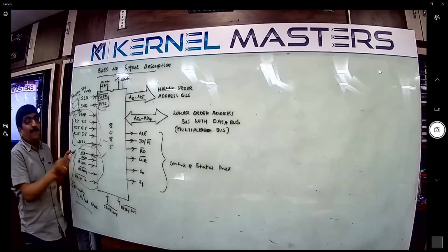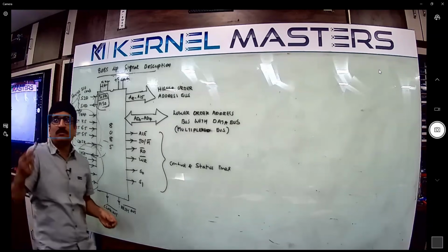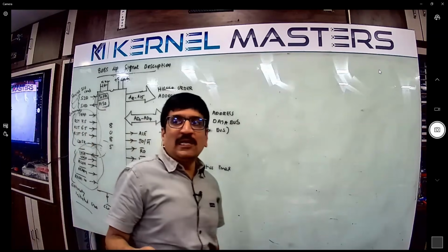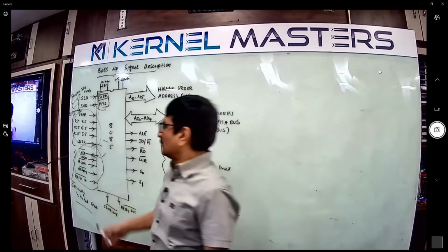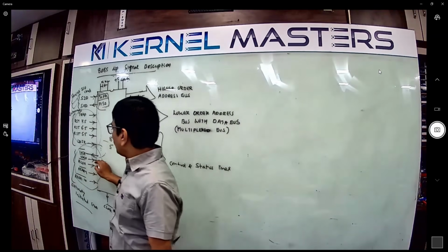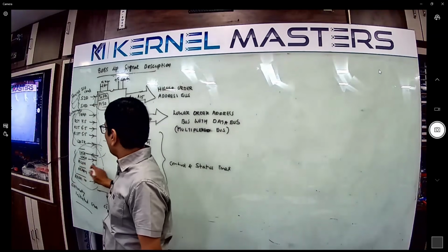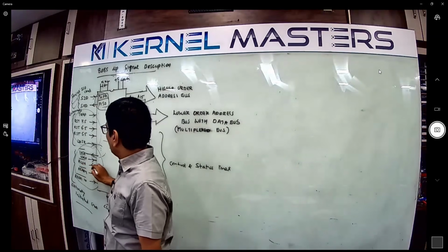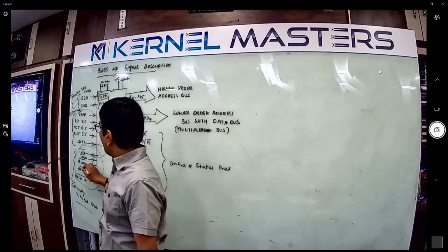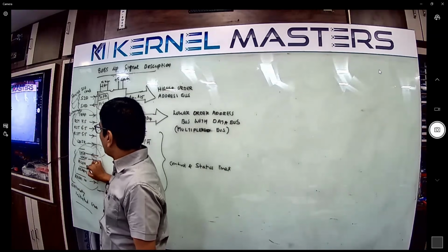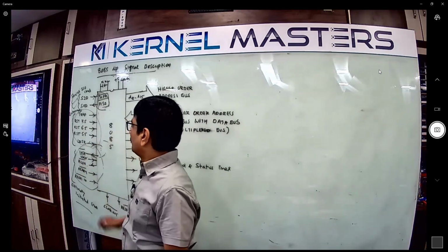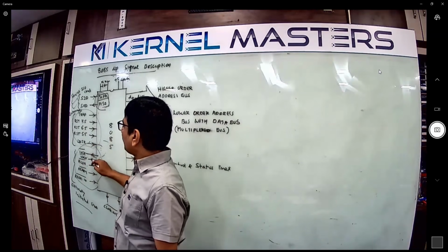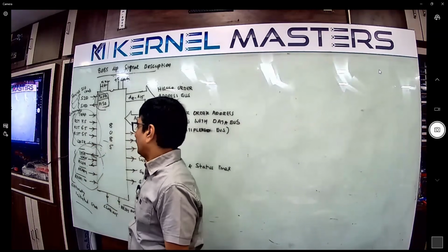Hold is a high priority interrupt, generated by the DMA, direct memory access. Whenever a hold interrupt occurs, the microprocessor gives a response, the hold acknowledgement. Hold has its corresponding hold acknowledgement, and INTR has its corresponding INTA. Every interrupt has a corresponding acknowledgement line.